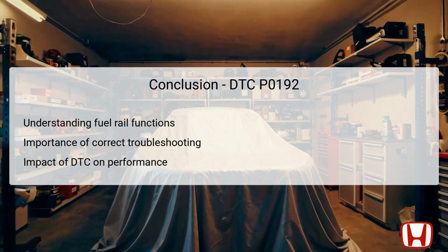Tracing the possible causes, such as an open VCC line or sensor failure, highlights the importance of thorough troubleshooting steps. From verifying ignition status to examining the PCM, recognizing the associated symptoms not only aids technicians in identifying faults, but also helps in communicating possible issues to vehicle owners.